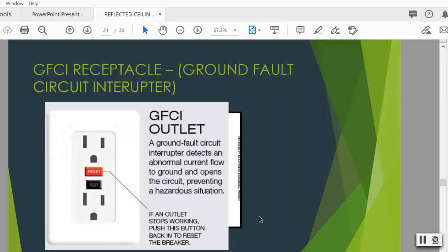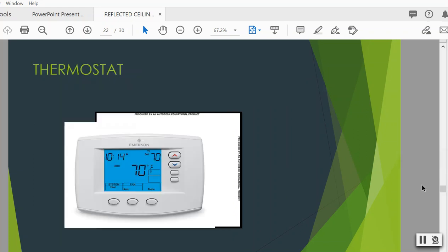And they're very handy. So if a breaker goes out, or if you notice a whole entire area, like your whole kitchen area, the electricity isn't working, first try to press that reset button and see if it pops back on instead of calling the electrician. Save yourself some money. So these GFIs have to be located wherever there is water or a hazardous situation.